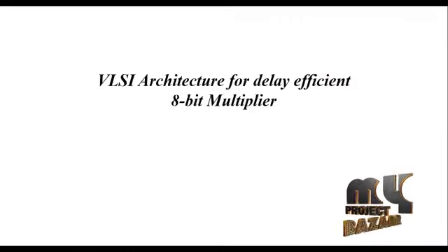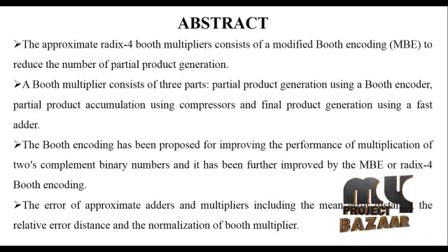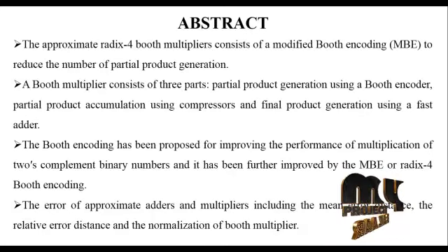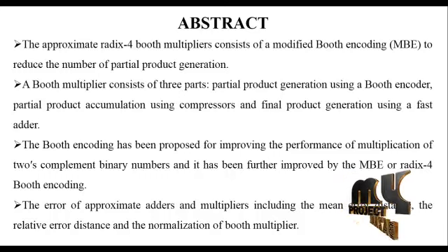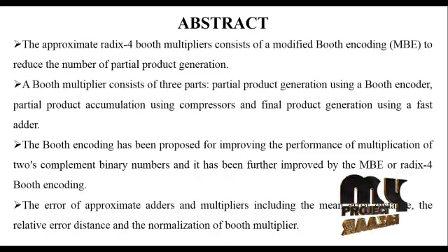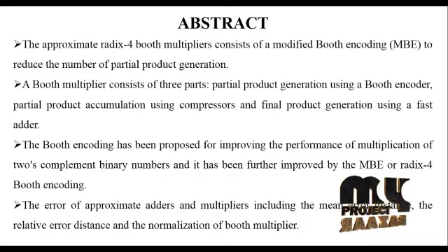Our project entails VLSI architecture for a delay efficient 8-bit multiplier. Our project abstract is based on an approximate radix-4 Booth multiplier. The radix-4 Booth multiplier consists of the Booth encoding process. We modify the Booth encoding based on the MBE to reduce the number of partial product generations.